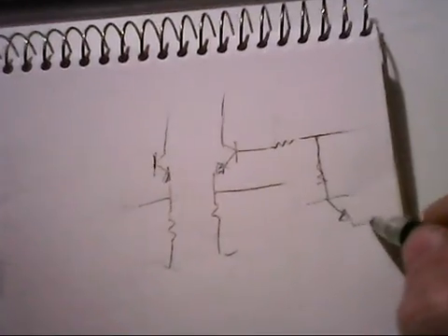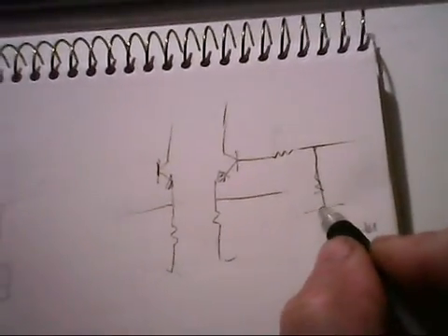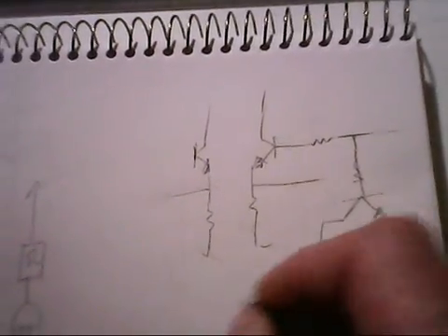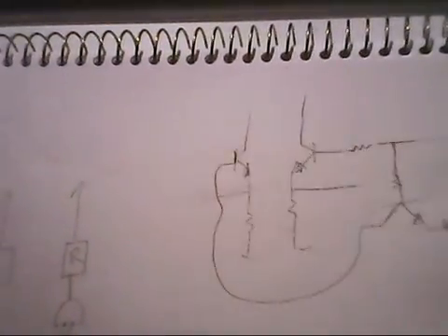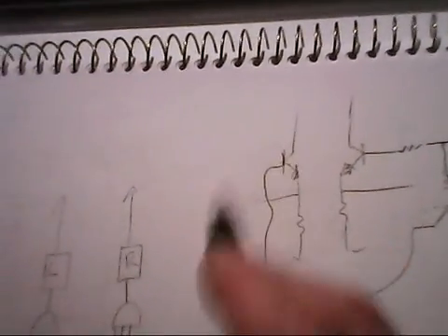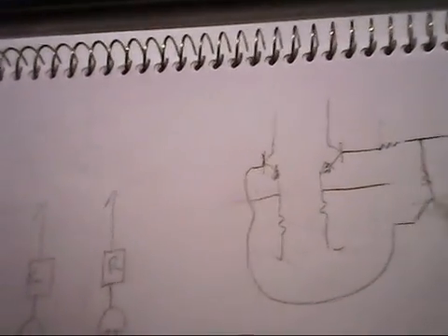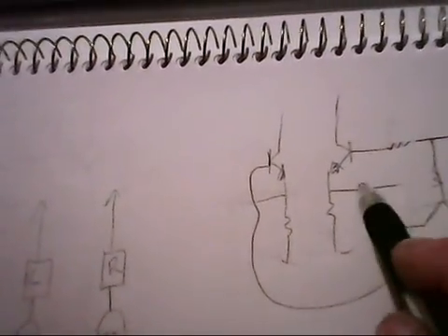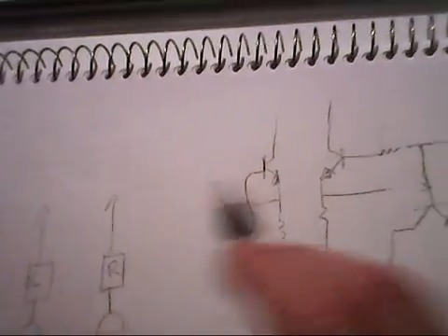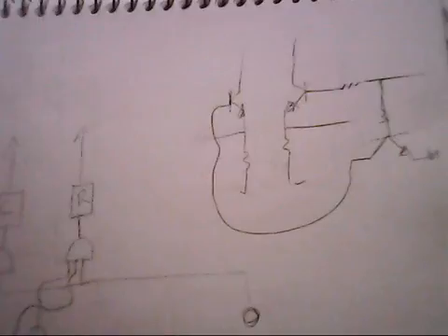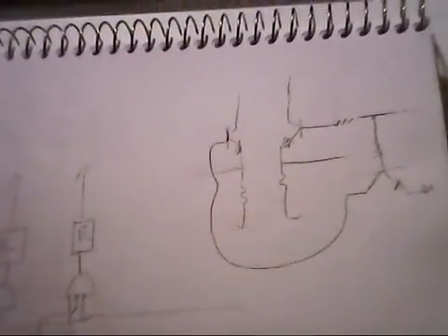At the same time, it's going to turn on the base of another transistor, which is going to be an NPN transistor connected its emitter to ground, and that transistor is going to cross-couple into the base of the opposing transistor that it's mirroring. And the same thing this way here, they'll be cross-coupled, so that when one input comes in, there's an output through that transistor here. But if both inputs come in, then the succeeding transistors on both bases will turn each other off by cross-coupling. I'll draw the whole thing and we'll look at it.